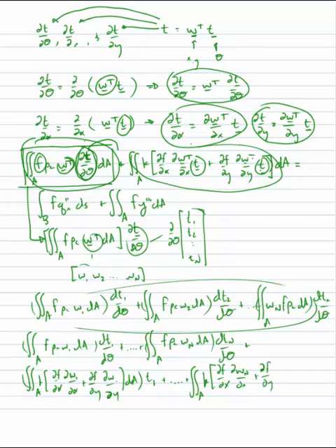A bunch of area integrals that we have to do, multiplied by either the derivative or the unknown temperatures, but we only have one equation, right? We have one equation for all of these different unknowns, and so the last thing we're going to end up having to do is we're going to have n equations, which means that we have to write this not just for one weighting function f, but actually for n different weighting functions, f1, f2, all the way through f sub n.